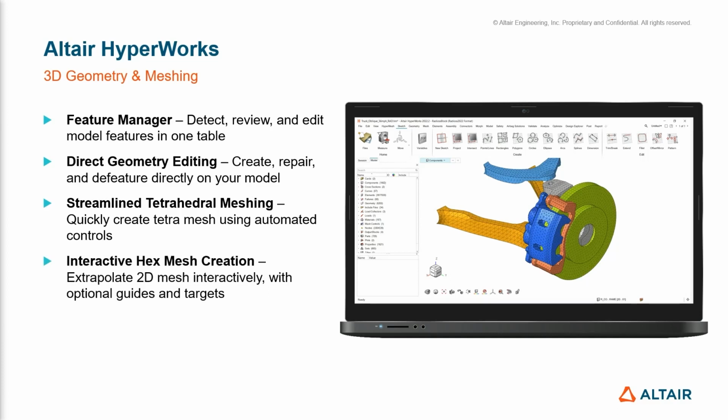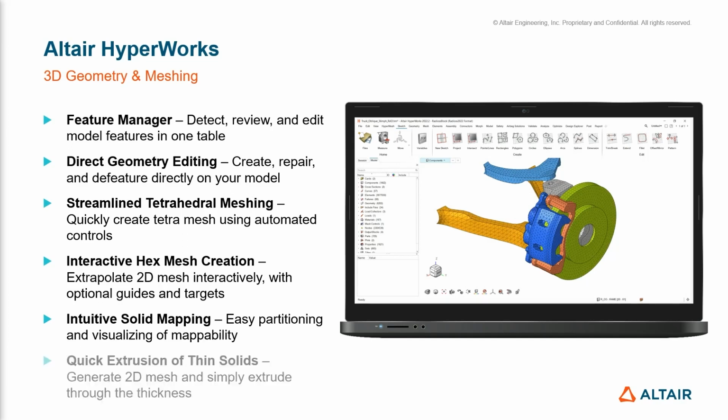HyperMesh also allows us to interactively create hex mesh, where we can extrapolate 2D mesh interactively with optional guides and targets such as using geometry surfaces or lines. We then also looked at intuitive solid mapping, where we used the combination of the geometry tools and easy partitioning and the visualization capability of HyperMesh for mappability. HyperMesh also offers quick extrusion of thin solids, where we generate a 2D mesh and then simply extrude through the thickness.